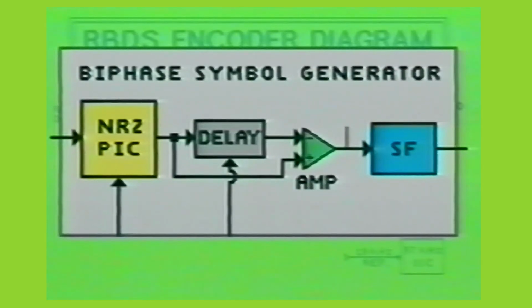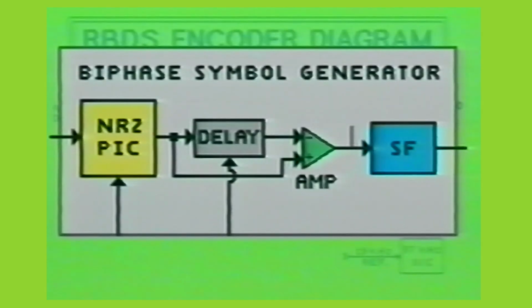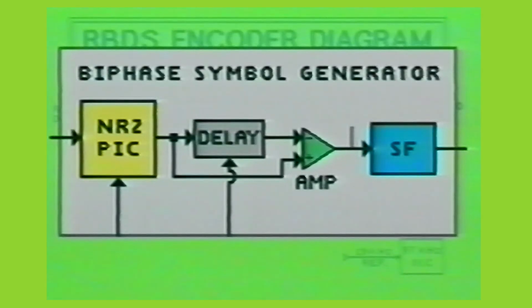The delay uses the 2.375 kHz clock frequency to offset the release of the delayed impulse. This impulse release will occur in between baud rate cycles of the incoming data. After the impulse travels from the delay to the negative input of the amplifier, it immediately reproduces an amplified but inverted impulse at its output.